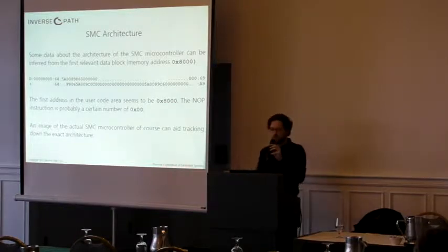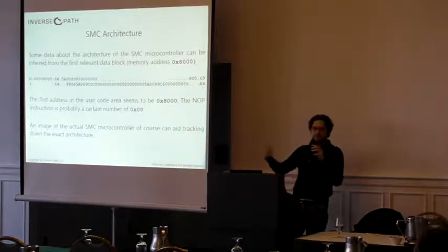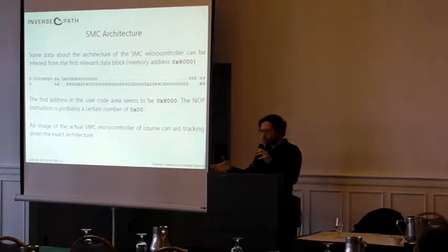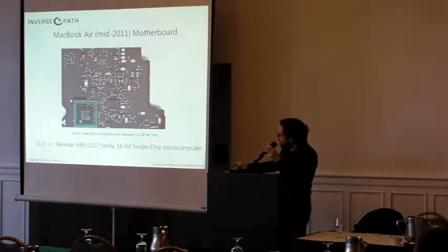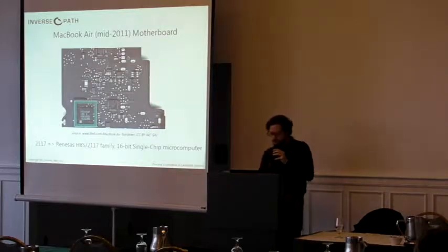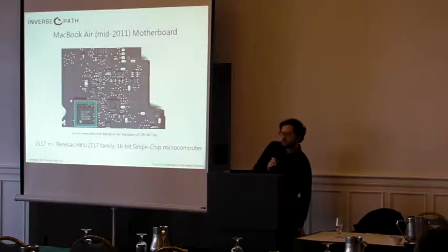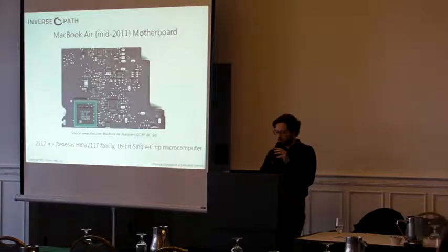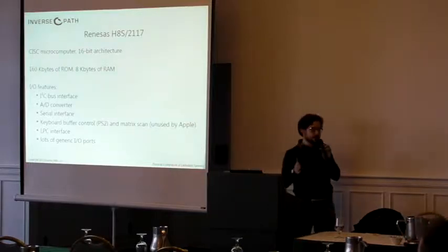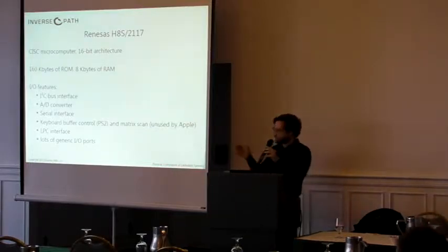And then, of course, if you have enough budget and effort to actually dismantle your laptop, you can also visually see what the SMC is, or you can go on iFixit, and iFixit will do it for you, which is really, really convenient. So we thought that this is the SMC unit, also because it's a Renesas H8S family 16-bit single-chip microcomputer, whose architecture is compliant with the data that we found earlier, and it is historically used as a system management controller. And it's pretty powerful.